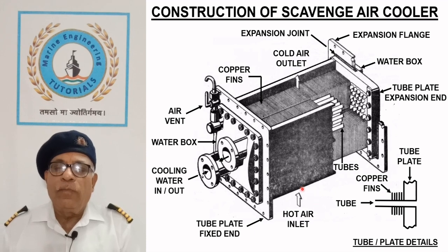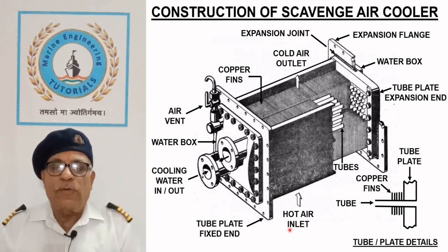Hot air from the turbocharger enters from the bottom, flows over the copper fins and gives its heat to the cooling water passing through the tubes, and cooled air is delivered to the scavenge manifold.